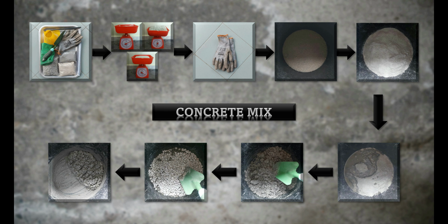Hydrophobic gloves are worn as one of the personal protective equipment (PPE) recommended to be worn before proceeding with the concrete mixing process. 0.689 kg of fine aggregates are put into the container and spread evenly. 0.328 kg of cement powder is put into the container and spread evenly on top of the fine aggregate. 0.1785 kg of water is added into the container.